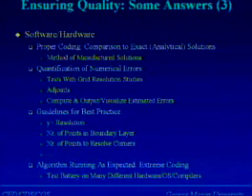Now, as far as software and hardware, the proper coding is done. The hardware you compare to exact analytical solutions, because you know what your partial differential equations are. Or there is what people are using a lot, the so-called method of manufactured solutions. So you give a solution that you say, this is my exact solution. Then you plug that solution into the Navier-Stokes equations or whatever equations you're solving. That will produce a source term on the right-hand side. Then you run your code with that source term, and you should be able to reproduce the solution that you put in. That's the method of manufactured solutions. There are some problems with boundary conditions and things of that nature, but they're being worked out.